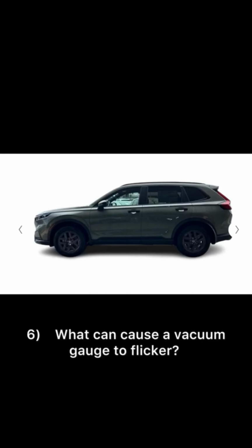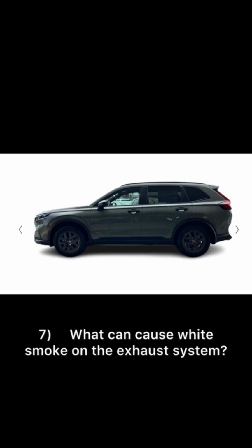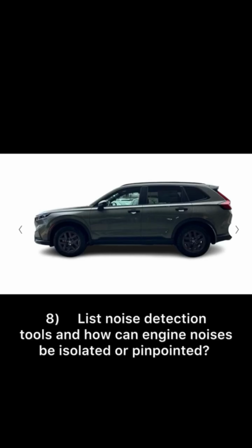6. What can cause a vacuum gauge to flicker? Issue related to one cylinder's function relative to the rest. 7. What can cause white smoke on the exhaust system? Burning coolant. 8. List noise detection tools and how can engine noises be isolated or pinpointed?